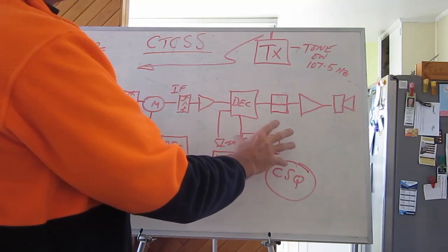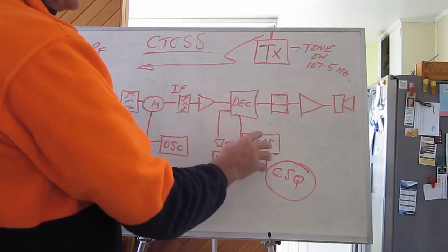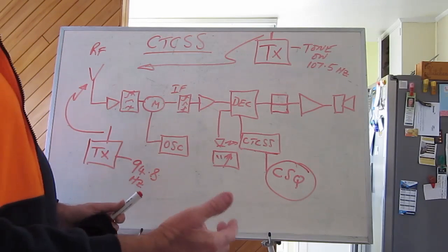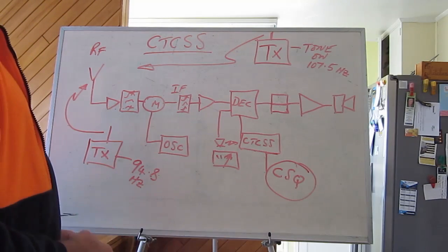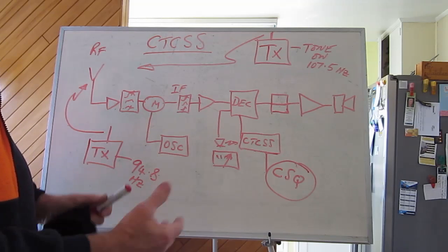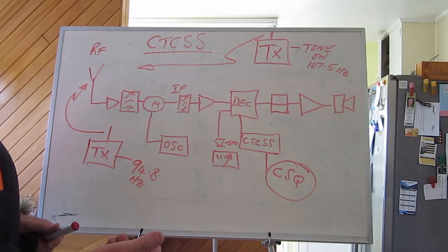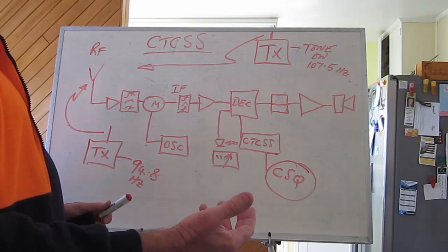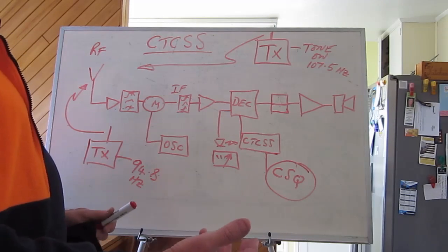And the user of this radio will also suffer from interference. Because one of the primary reasons why you put CTCSS on top of signals is that 9 times out of 10, interference, which is generated by man-made pieces of equipment, doesn't have CTCSS tone controls riding on it.